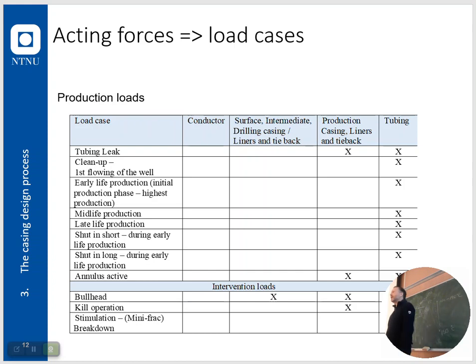So we always have to control our annuli, bleed them off as we heat the annulus. In this case, for old wells it helps a little bit to have a small cushion of gas on top, because the gas compresses and the pressure doesn't go up as fast, right?